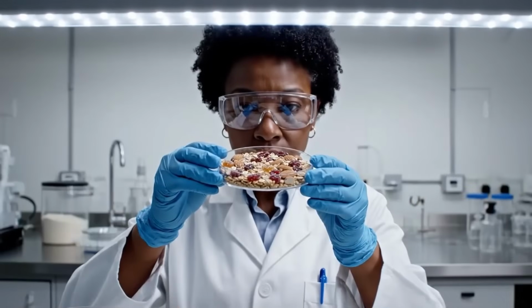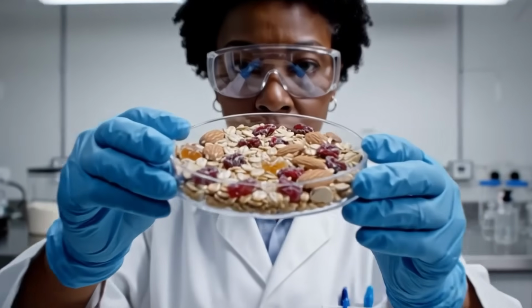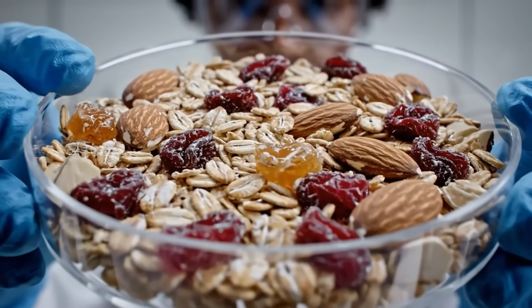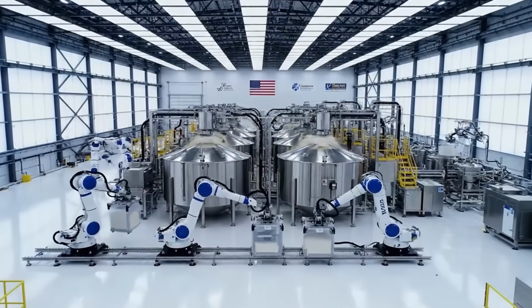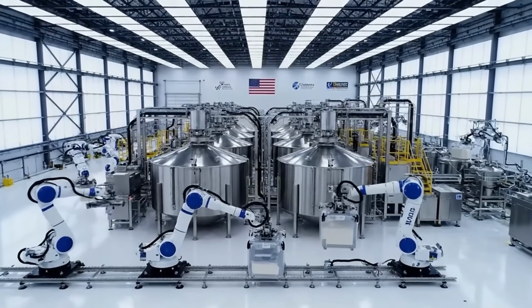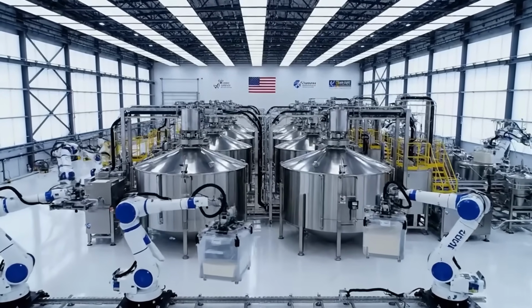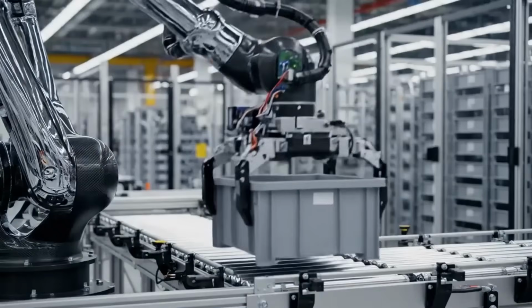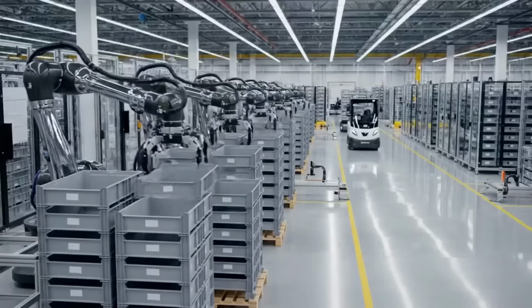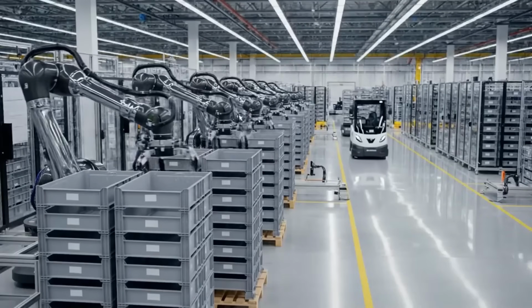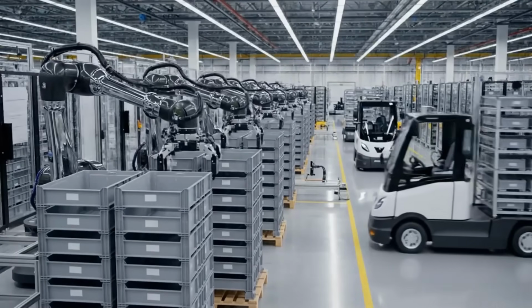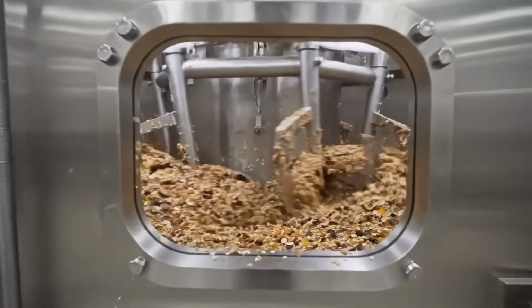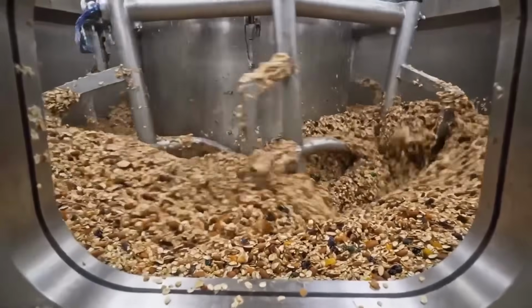The binder is heated to drive off water and to raise viscosity. Time and temperature are controlled because overheating darkens sugars and changes flavor. When the binder reaches target viscosity, it is cooled slightly to a mixing temperature that will not damage heat-sensitive inclusions. Cooling also prevents excessive softening of oats during mixing. Flavor addition often occurs after this cooling step.